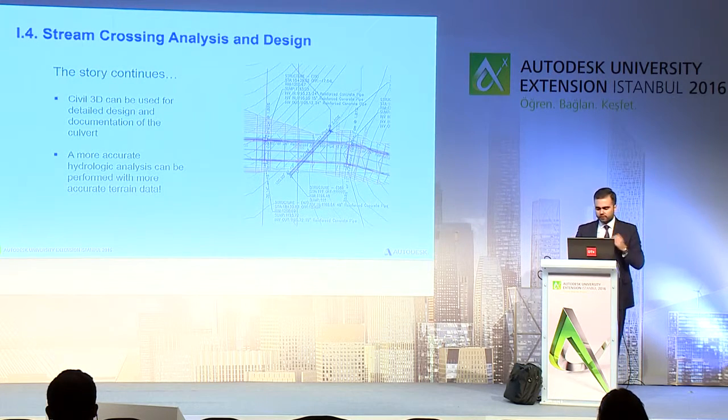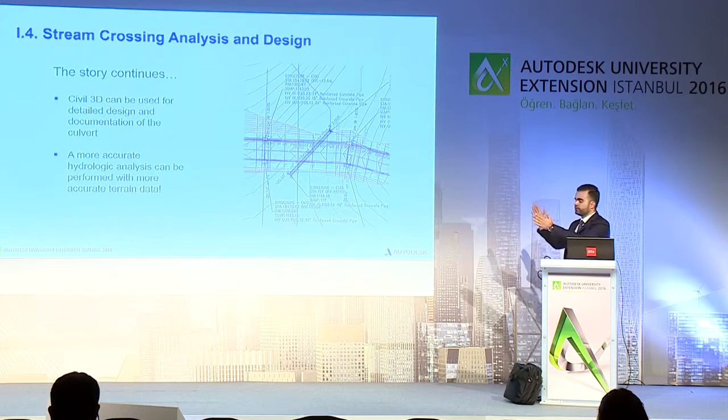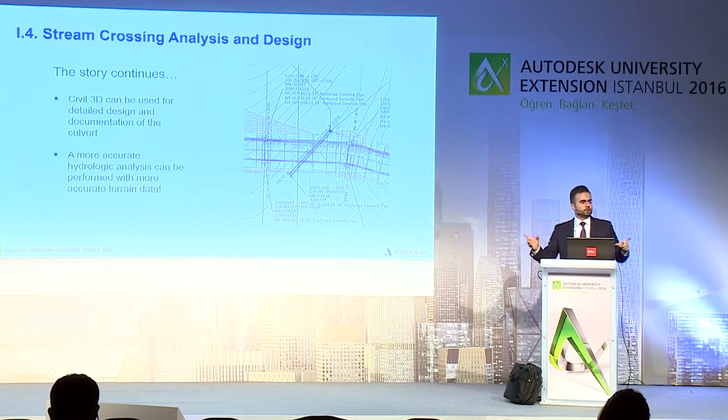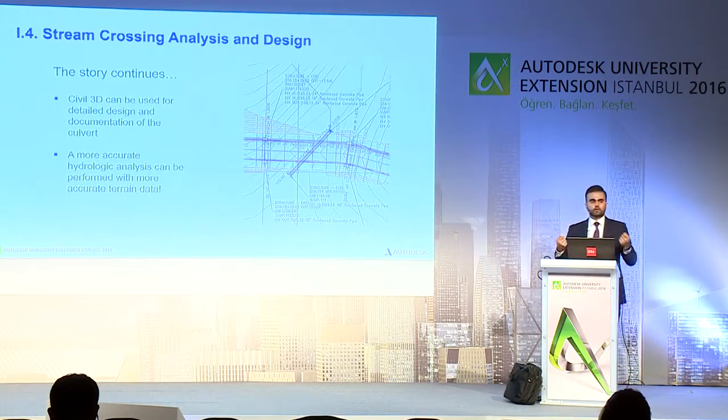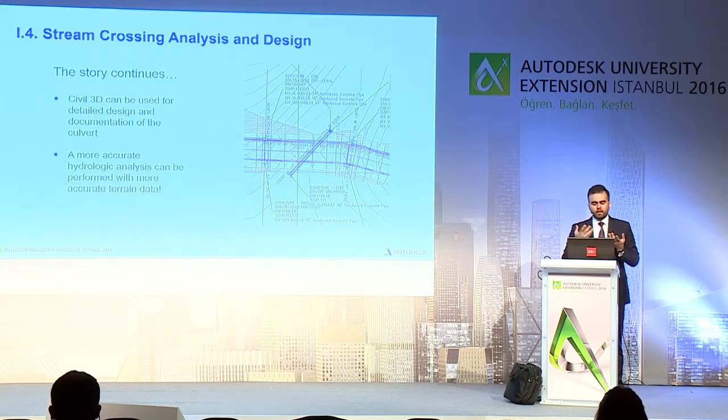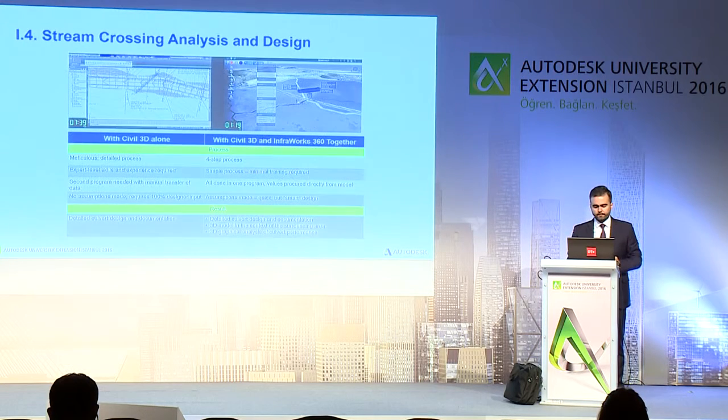And then the story continues. We get that from InfraWorks, we open it in Civil 3D, and thereon we can create the cross sections and the sheets for the construction documentation. So this is why both tools work together. The power of InfraWorks, again, is utilizing the cloud, the computation that is done in the cloud, and pushing that back into your machine to show it visually in 3D, whereas Civil 3D is perfect for detailing and documentation.